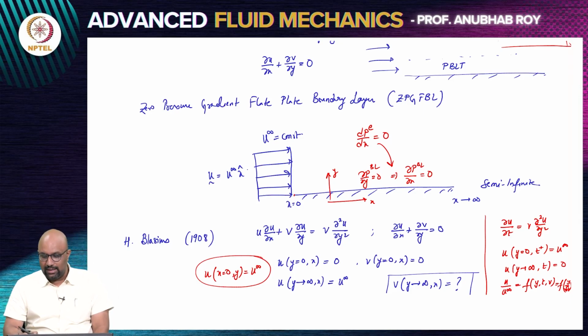If you remember, in the unsteady problem, we finally had the 3 boundary conditions becoming 2 in the similarity variable. There were just 2 boundary conditions. 2 of the boundary conditions collapsed and became 1. So in the flat plate boundary layer, you can solve this problem exactly. Like the equations that you have here, you can go ahead and solve this numerically. This is perfectly fine. You can just crunch it into a computer, solve it marching in x, define what is x equals 0, give an inlet, and then watch what happens.